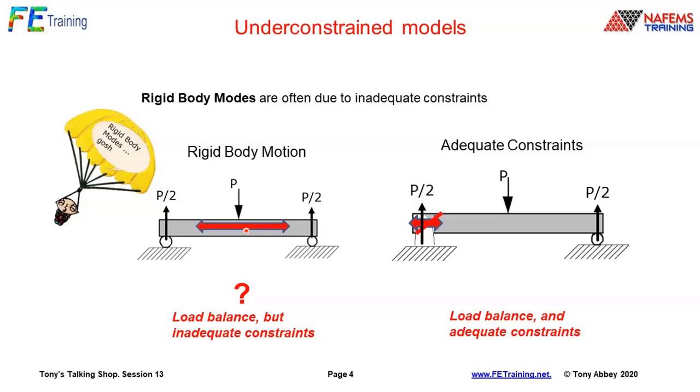In a more physical way, you could say it's searching for any possible rigid body mode. So if I were to put a load coming from the left, then now I've got something which is not a static solution, it's a dynamic solution. Force equals mass times acceleration. So we come to the right-hand diagram, and we put that constraint, a lateral constraint I've tried to indicate there, even though it's nothing to do with the particular load path I'm interested in at the time. There's me, maybe a week later, or somebody else picking up the model, who could put a load on going from left to right, and then we get caught out.